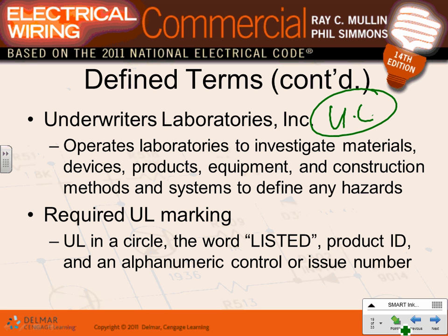A very smart, competent group of people sit in a big area with a lot of equipment and test it, based on what the manufacturer is telling us that it can do. You say this light is going to create 2% harmonics, right? Can you measure that it's 2% harmonics? 99% of the people have no idea how to measure that. Take it to UL, go power that thing, put meters on it, measure, yep, it's 2% or less. Check, UL. Does that make sense? Without them, it's hard to install equipment.